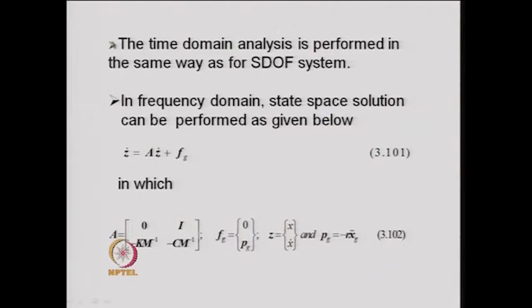So, we can solve the problem for the system in the time domain as well as in the frequency domain. In the time domain one can solve the problem using Newmark's beta method, or Duhamel integration for a single degree of freedom system.